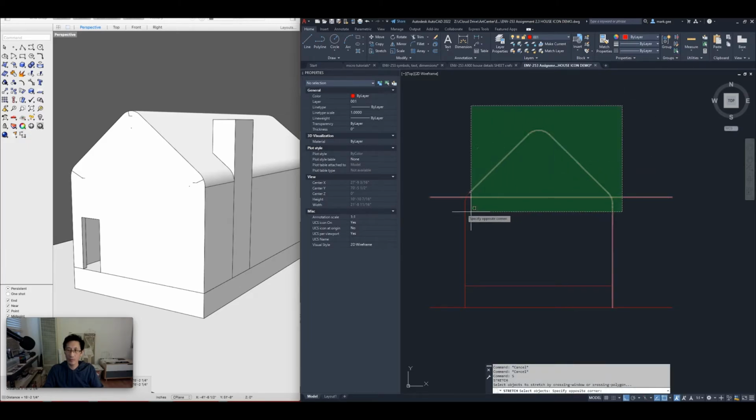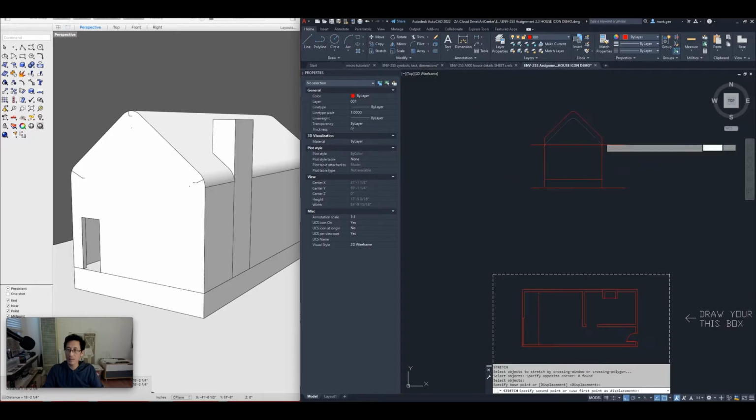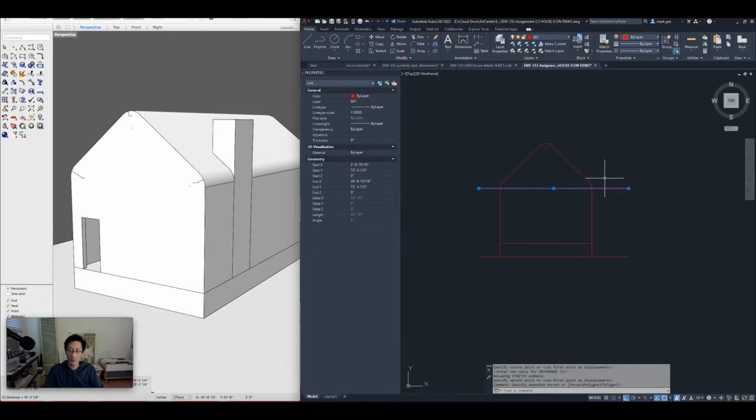and I'll draw through the points that I want to move, which is this set of points, which is everything from the bottom of those curves up. I'm done selecting, I'll hit spacebar, I'll move in here a little bit, grab, and snap to and grab that point, and now you see what happens is I can move all of those points I selected. I can move them anywhere I want, but I really just want to move them up straight so that it's not perpendicular to that new line I made there. So that has set the roof at the proper height.